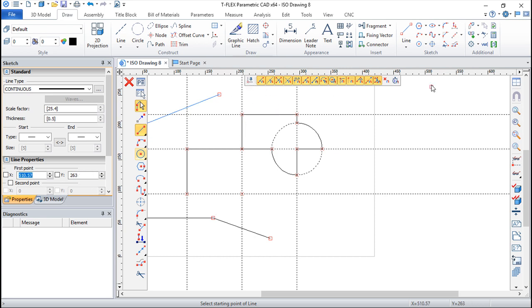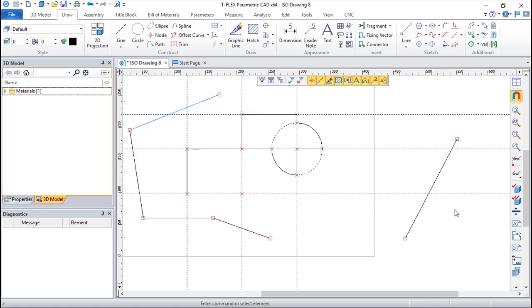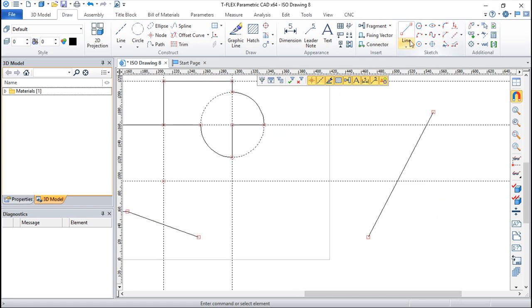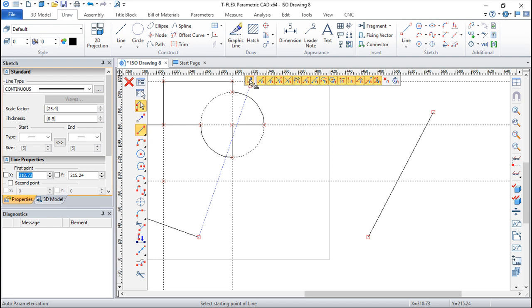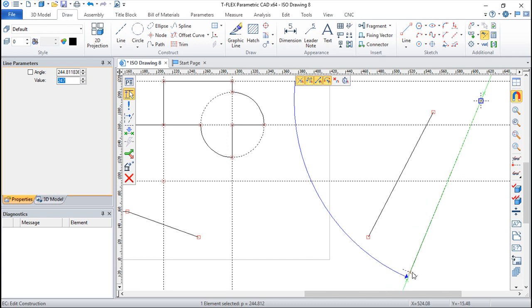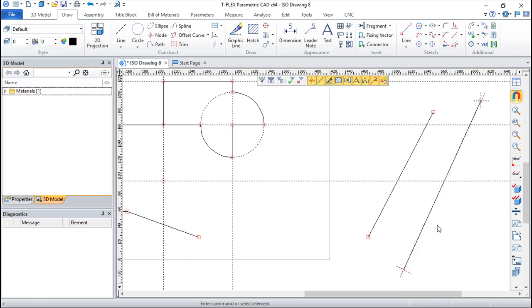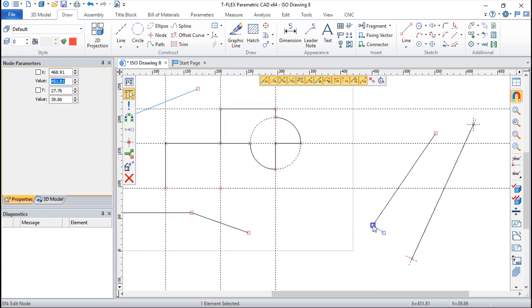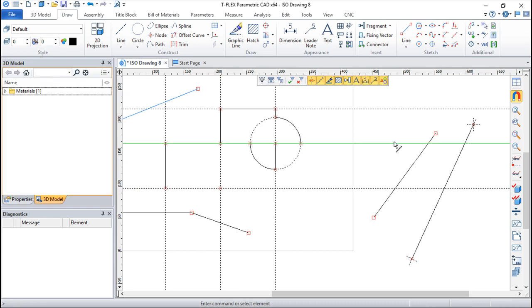If it is not selected, then when we make a line, you see a line; this is the free mode. I can create the same line, but if I turn this on, it's a little different, because now you can see that I have some construction lines that the system added to the endpoints of my line. And this is a parametric thing because it's connected, or parametric, regarding something. It may not be what we want, but it has that parametrization done. This one is completely free.